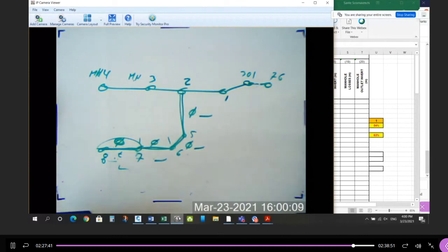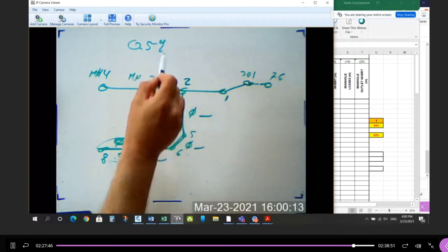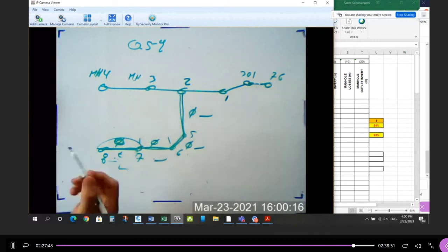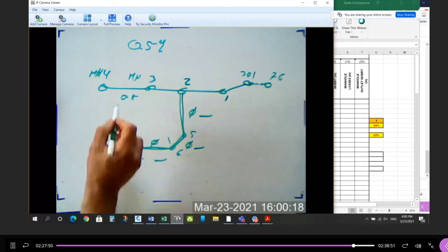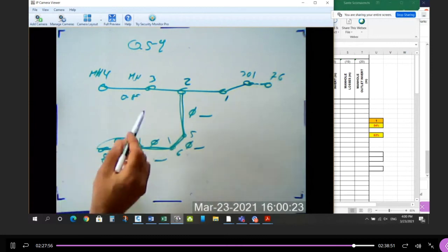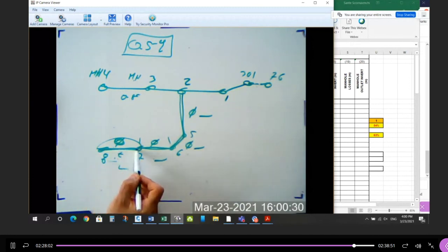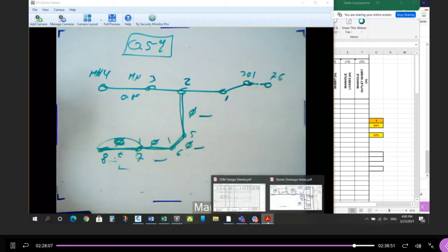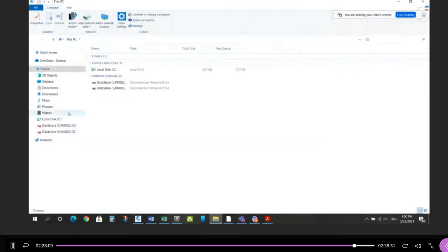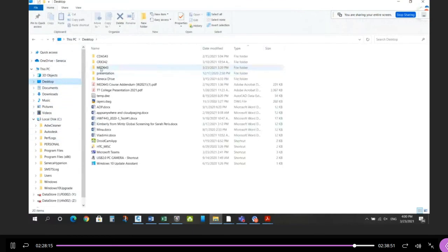So make sure to begin with, you remember the minimum slope on the road is 0.5%. So make all the pipes to begin with 0.5%. Make all the pipes, including the dead ends at the top. In sanitary, we made them steeper. Remember 1%? For storm, make them all 0.5% to begin with, and then just play with the size. Change this size. A 300 is the minimum pipe size. How do I know? Check the standards. So if we go to the standards for municipality, for desktop.